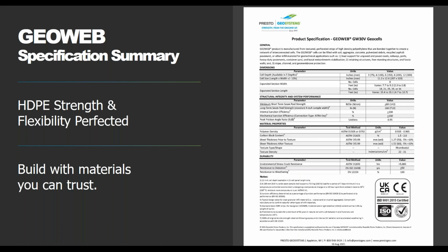So in order for a geocell system to perform uniformly, it is critical that both the factory welded junctions, so those internal seams that I mentioned earlier, and field joined junctions that connect the individual panels. So these are a mechanical connector connecting individual panels to create a single whole system. And you want both of these junctions, both internal and mechanical, to perform at a level that's going to be commensurate with the cell walls. So you want the junctions and the cell walls to be equally strong. You don't want one to massively outperform the other.